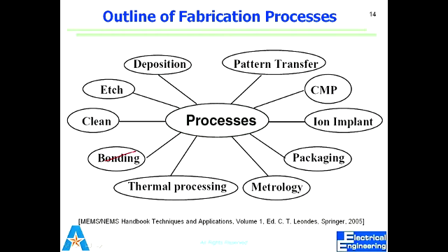So I used one mask to do this, that mask goes away, I do something and I put oxide, and now I use the second mask, but it has to be, now the mask is gone, but its pattern is there. So the second mask has to align with the pattern, so my leads can come out exactly from those two places. Does it make sense? So pattern transfer is a very in-depth thing. So we use lithography to do that. Optical lithography is where we use light, ultraviolet light, to transfer the pattern on the surface.